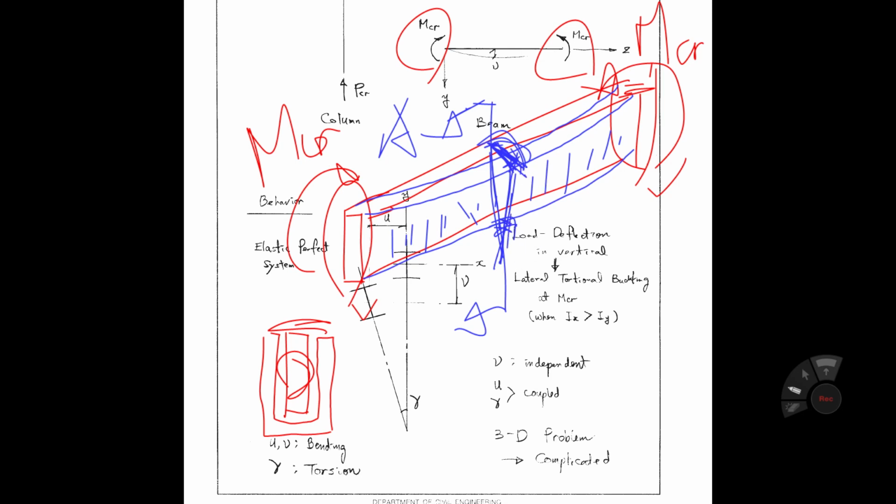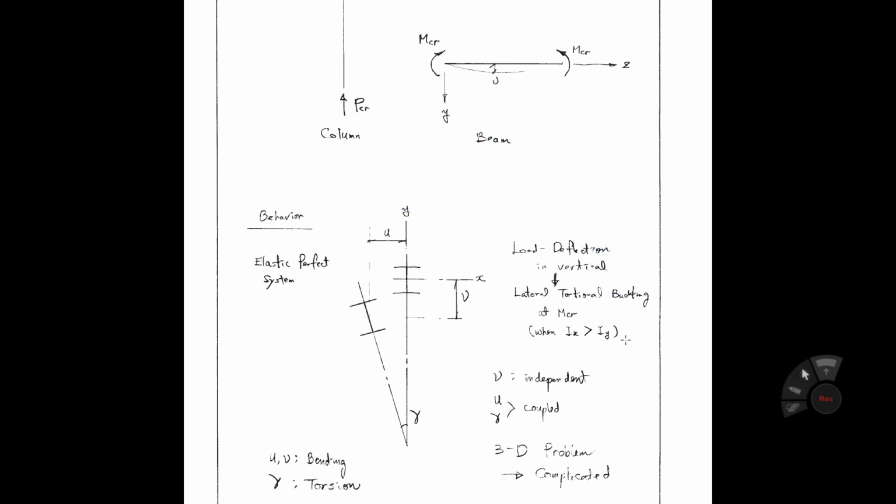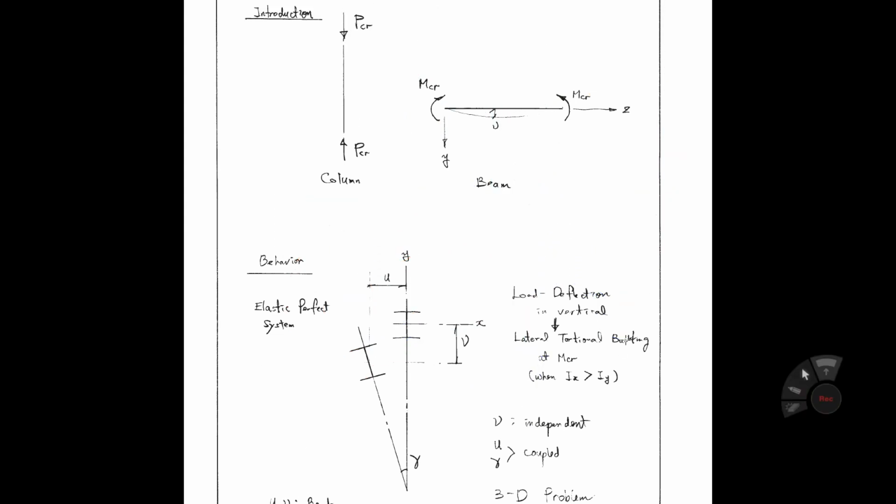It is beam buckling. It is three-dimensional behavior. Along the member, we have to consider this direction, and we have to consider this lateral direction also. And then we have deformation, as you see, vertical deformation. So it is a three-dimensional problem. In fact, lateral torsional buckling behavior is relatively complicated compared with column buckling. As you see, for column buckling the shape is like that, with X direction and Y direction. This is a 2D problem. This beam involves the Z direction and Y direction.